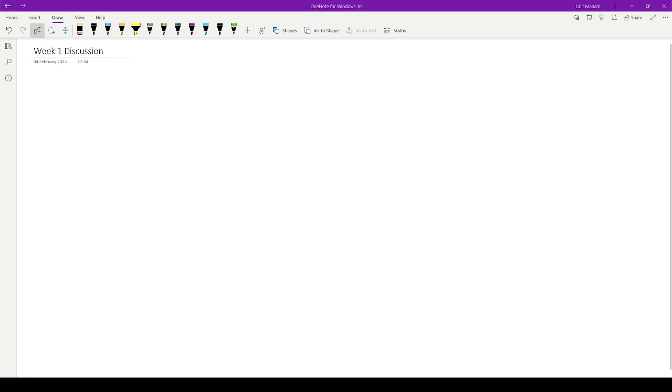So we have done sampling. The next is quantize. Okay, what does quantize mean? Arranging those samples according to the intensity value, discretizing it between an upper and lower bound, putting all the intensity values in a given number of buckets. Let's say we have 8 bits to store the intensity values. Then we will have a certain number of buckets where we could put all the intensity values.